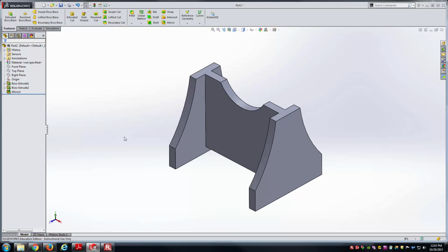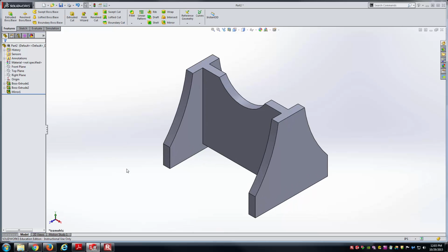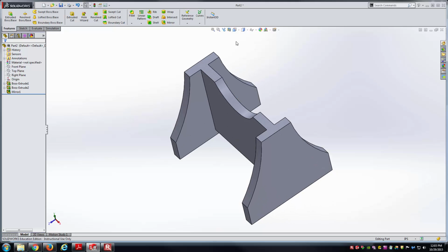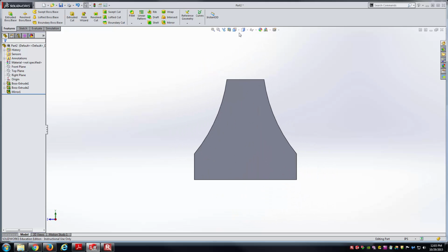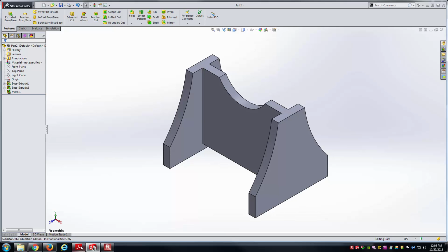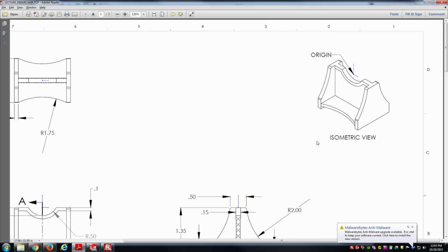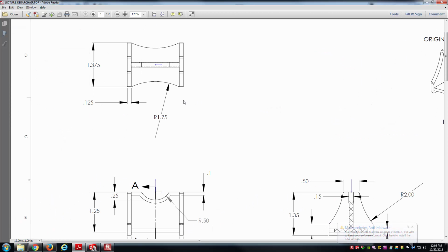So here I can go ahead and check. It looks like I've got the correct isometric view, and the origin's also located correctly for me. So next step on this will be the floor feature. Can have this floor that's elevated off the very bottom datum. And so this floor, I can get all the dimensions I need from the top view here.